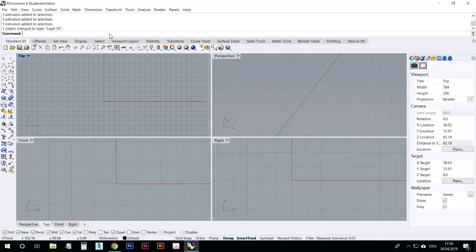If you are using a different language setting in your Rhino, you will notice that if you try to type save, some other suggestions come up based on your language, right? But you can always override that by pressing underscore before you type. So _save, and then the English version will appear, as a matter of fact.